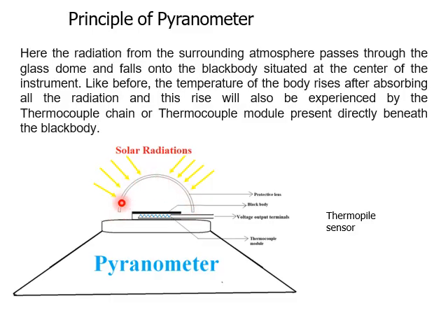And why is it particularly glass? Because glass is opaque to infrared rays. That means this glass dome will only allow the light to pass through, but it will reject the heat wave that's coming along with the light wave. Besides that, this glass dome gives protection to the thermopile sensor inside, and in some cases they use a double layer of this glass dome also.